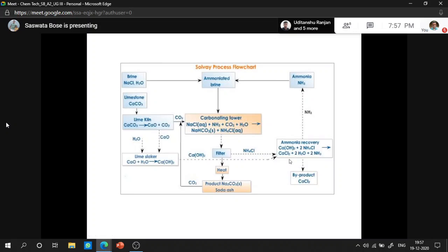How is it being done? The filtered liquor from the rotary filter is sent to a pair of ammonia stills. It is not so easy. The ammonia recovery section consists of a pair of ammonia stills. In the first still, free ammonia is driven off by a steam heated reboiler, and from the bottom we get combined ammonia, which is fed to the combined still.